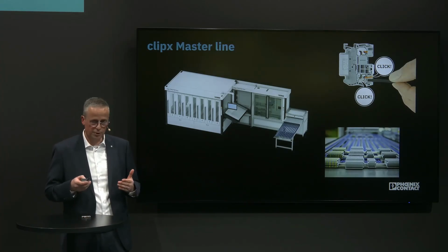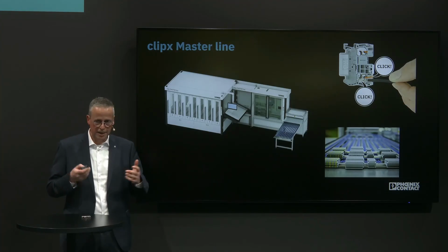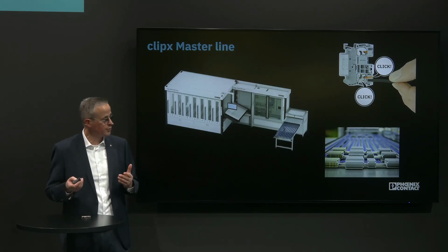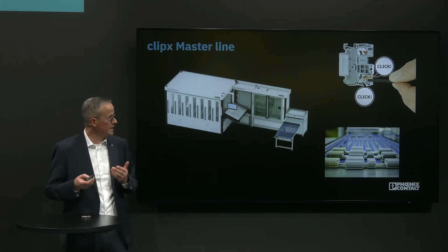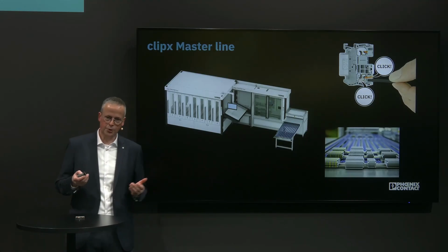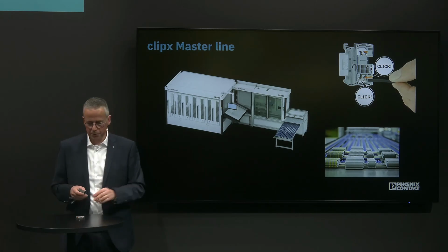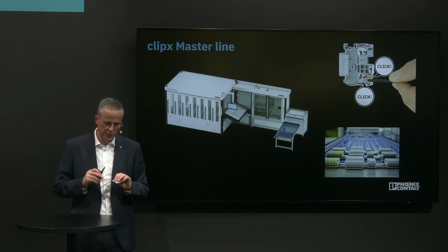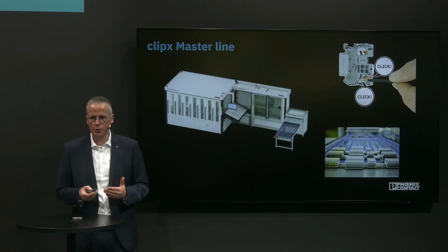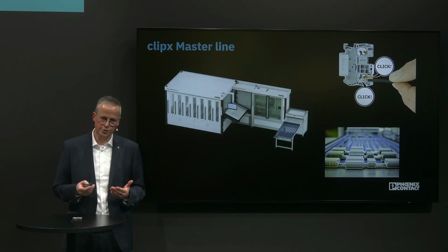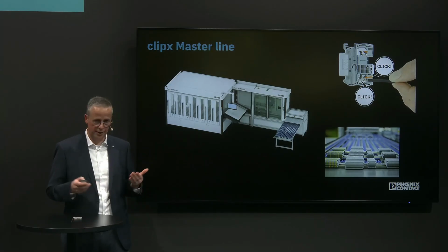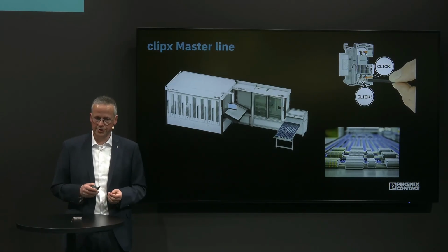And this is something, when we are talking about automation, there are camera systems often involved and can be used for this and have to be used for this. And this is also a benefit we see from the XT termination technology, because you have an optical indication for camera systems that the conductor is connected. And what we also have, and this is also a difference to push-in, the insertion force of these conductors is very low compared to push-in termination technology. And also this is beneficial for topics like automated wiring. And this at the end increases the efficiency in control cabinet.